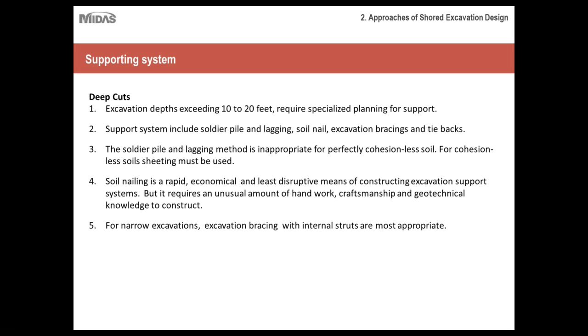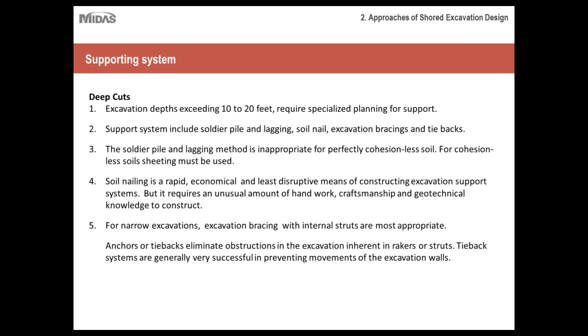For narrow excavations, excavation bracings with internal struts are most appropriate because they are narrow in nature and they are deep. You can't really go in and do soil nailing, so it is better to have internal struts to provide the required support.